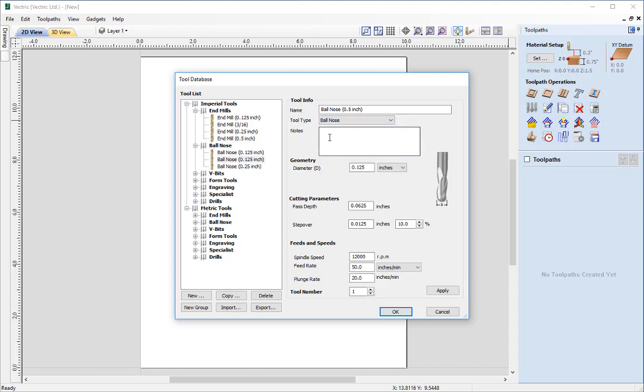We then have the option to add some tool notes. So if we have any specific comments regarding the actual tool itself, we can put them in there. These could be utilized by extracting that information and placing it in the post-processor code, so that when we go to run the toolpath, if our control software is compatible with tool notes, we can flag up those notes upon running that toolpath. This would require, however, editing of the post-processor files for your particular control software itself.